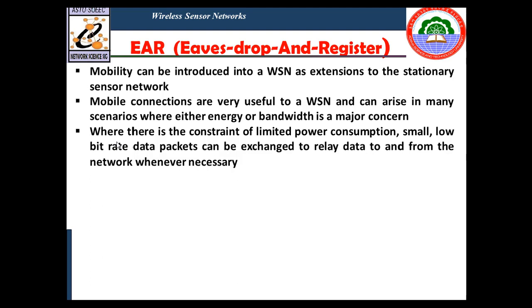These nodes are engaged in the process of finding their neighbors and wake up at random times. Upon waking up, each node listens to the channel on a fixed frequency for some random time duration. The node decides to transmit an invitation by the end of the initial listening time if it hasn't heard any invitations from other nodes. This is what happens to node C, which broadcasts the invitation message like this.